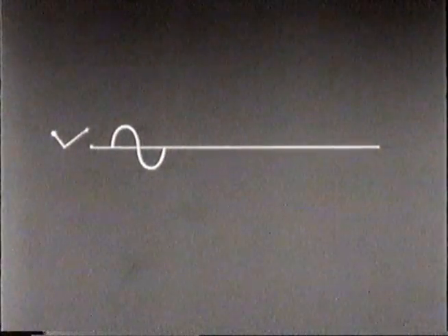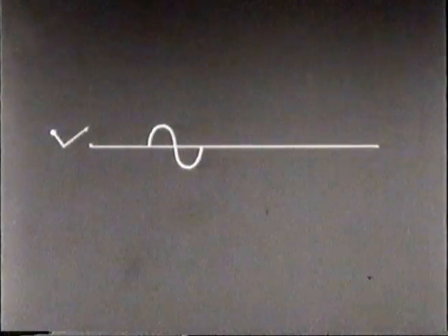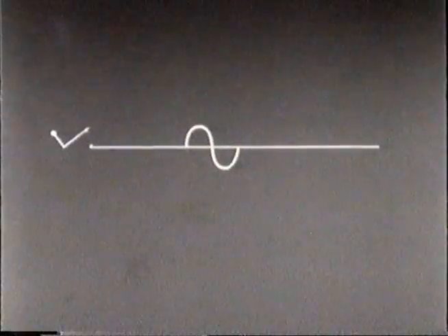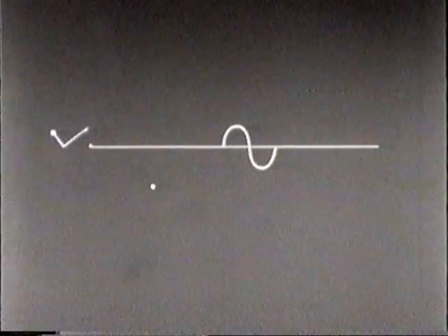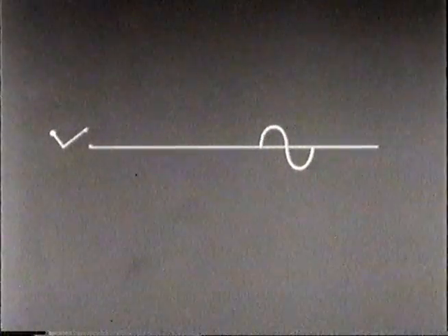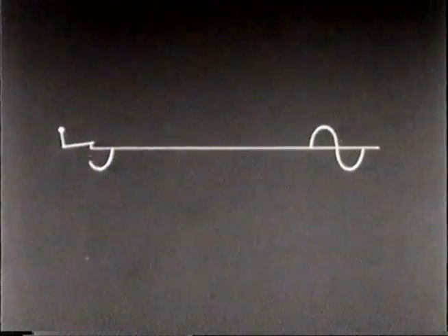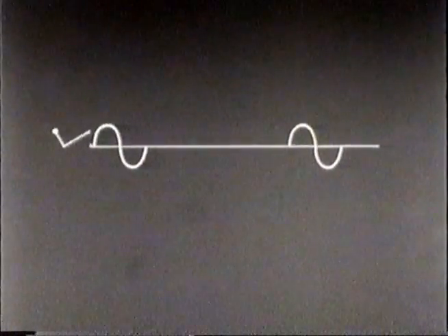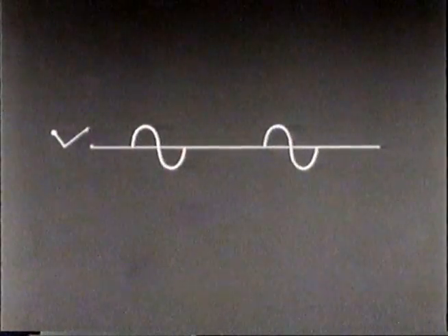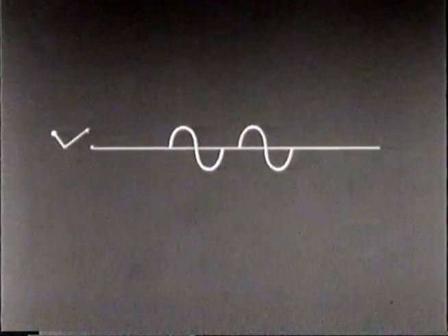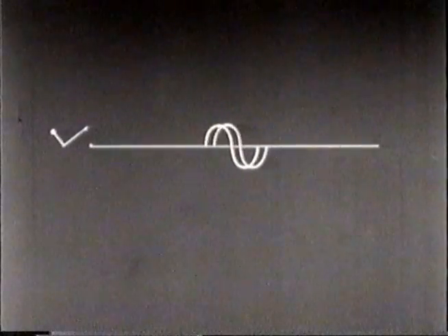In diagram and in slow motion, we may picture a high-frequency impulse moving over a wire as a traveling wave. A traveling wave on a conductor keeps its speed and form until obstructed in some way. If such a wave comes to an abrupt end of its conductor, that is, to a position of infinite impedance, it is reflected and turns back in the opposite direction. If, however, another wave following the first one meets the reflected wave, the two unite and the standing wave results.